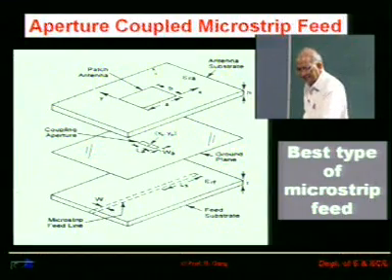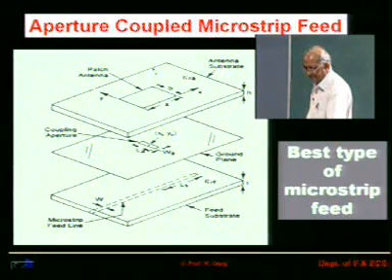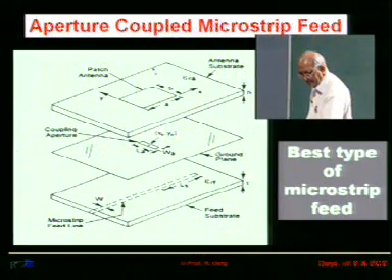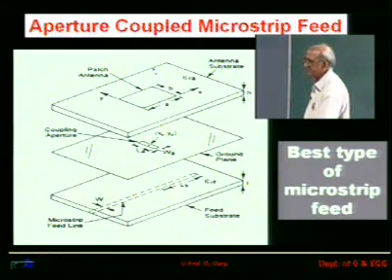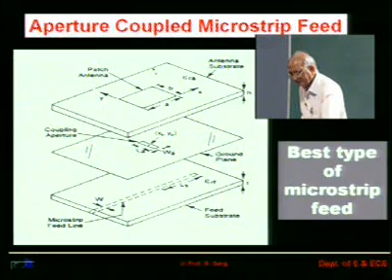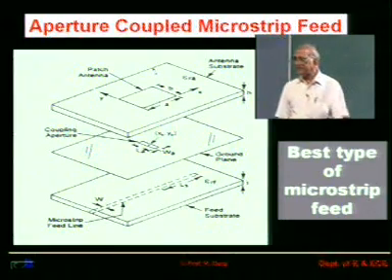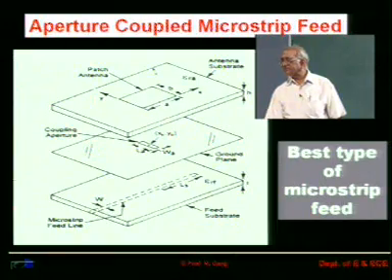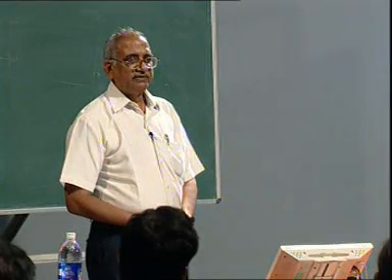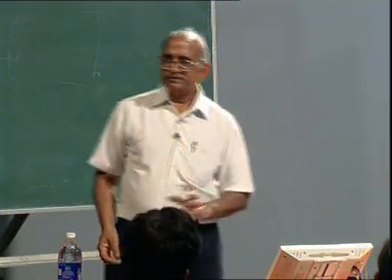And as far as the 50 ohm part is concerned, the input impedance should be 50 ohm, because your feed impedance is 50 ohm. That is taken care of by the design of this slot part, because the impedance will get modified or transformed from your patch impedance to the 50 ohm through this coupling mechanism. Okay. So, in this feed, there is a transformation of impedance from the 377 ohm to the 50 ohm at this particular point, right.